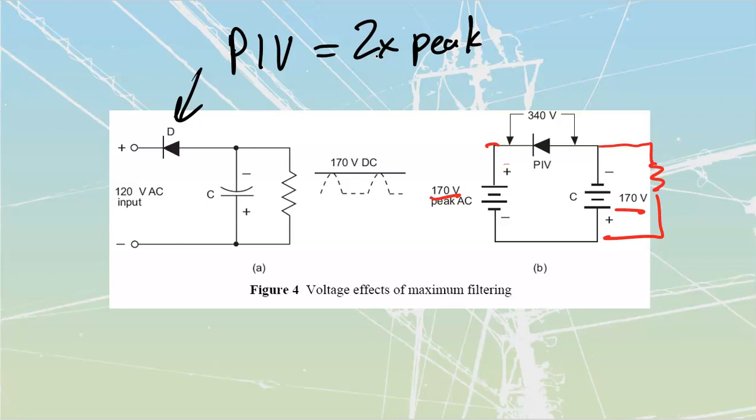When you are working on these circuits, there's once again going to be that little safety blurb that they put out about making sure you discharge them. Caps hold values of voltage. We see that, when we do hold this value of voltage, it should discharge through this. But if that's going to be a high impedance load, or if this is a load that has a switch in line with it, and that switch is open, that charge could stay stored on top of there, and you put yourself at risk if you start playing with that circuit. Be very careful with your capacitor circuits.